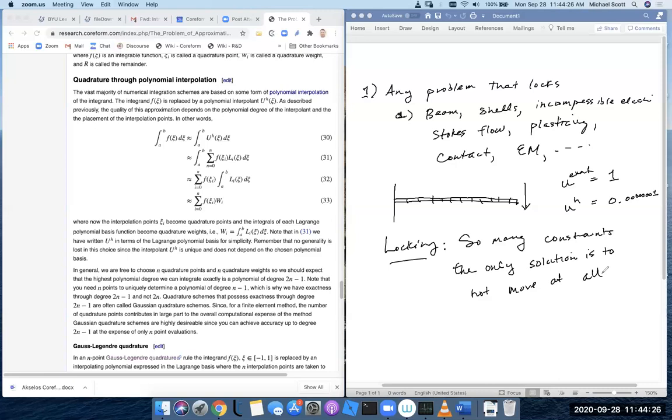And that relationship is what's encoded in what's called the inf-sup condition, or the LBB condition in mixed methods. And so that's why in finite elements we use reduced quadrature, because really it's a way of doing a mixed method with some other space in an easy way.